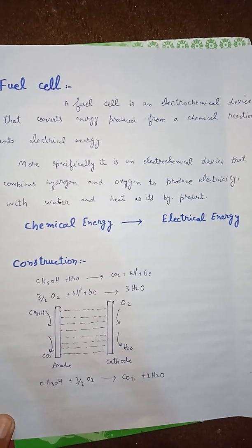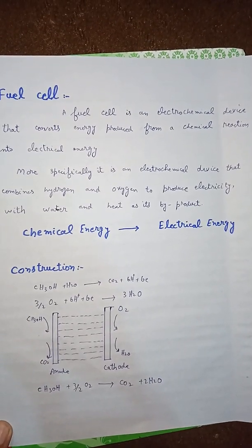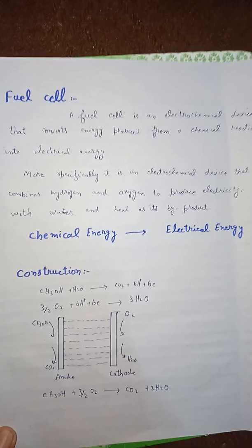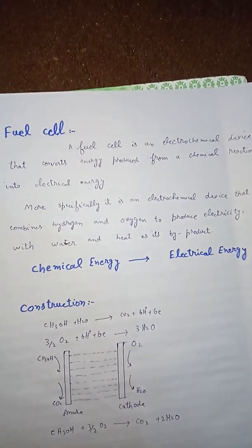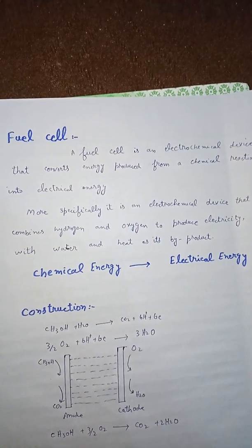First part of construction is the anode. The negative post of the fuel cell conducts the electrons that are freed from the hydrogen molecules so that they can be used in an external circuit. Etched channels disperse hydrogen gas over the surface of the catalyst.